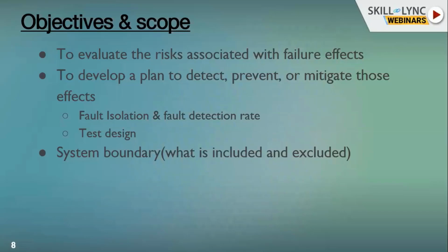And if the designer has taken the proper action, that failure doesn't happen. So in test design you prioritize which system components you should be stressing more in your test, and which way you should be stressing that component. That's what comes from FMEA, that helps the test design.